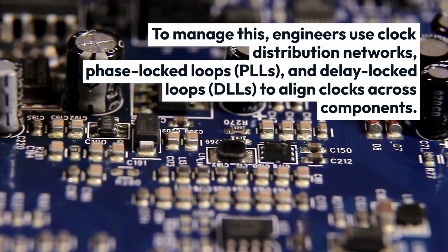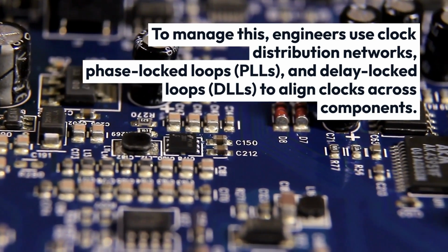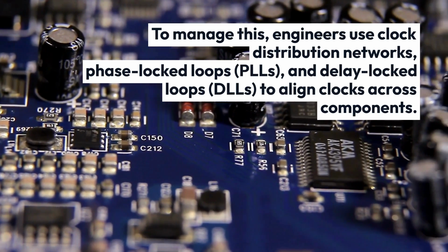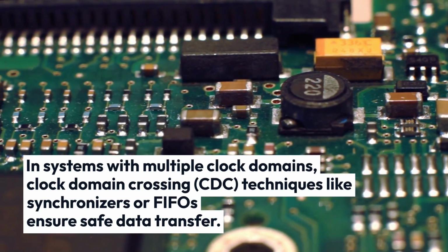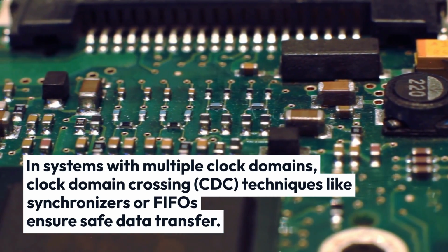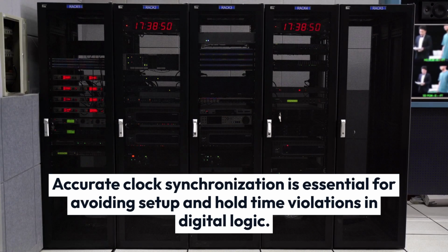To manage this, engineers use clock distribution networks, phase-locked loops (PLLs), and delay-locked loops (DLLs) to align clocks across components. In systems with multiple clock domains, clock domain crossing (CDC) techniques like synchronizers or FIFOs ensure safe data transfer. Accurate clock synchronization is essential for avoiding setup and hold time violations in digital logic.